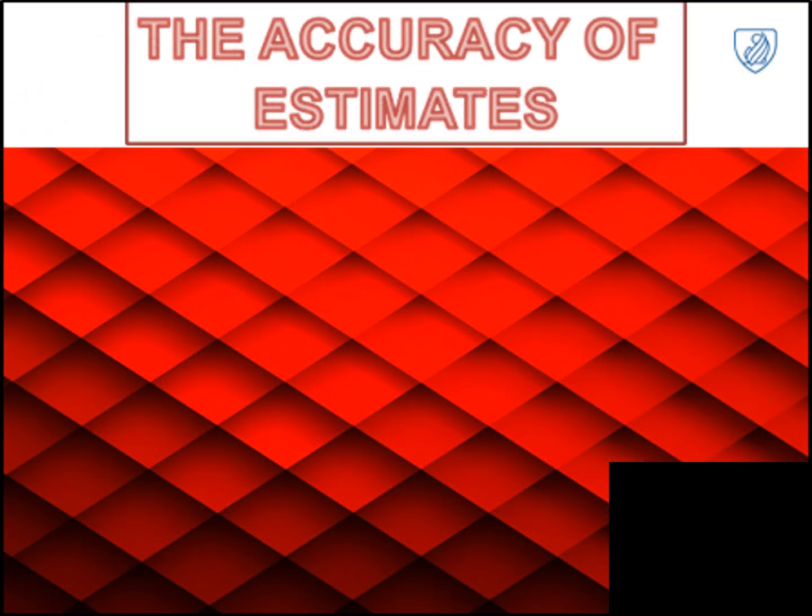So your accuracy of the estimates is very important. What type of rate historical data will you be using? Will you use the same rates that apply to Cape Town, for instance, in Bloemfontein, which will not be the case because the standard building rate or the market differs from here to there or anywhere else in the country. Certain areas might be cheaper, or certain items might be cheaper in certain areas because it's manufactured nearby. If you're working, for instance, in the Northern Cape on the mines in the Kuruman area or so, you will have to take into account the transport costs to that area and so on.